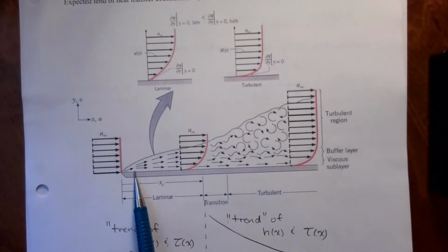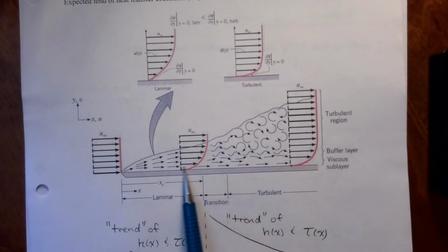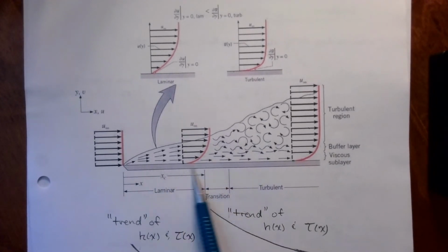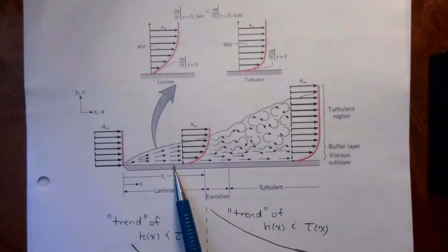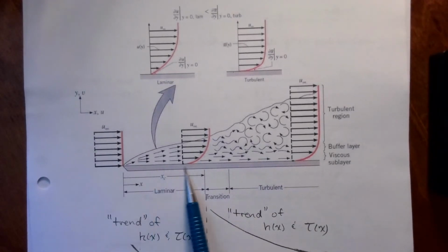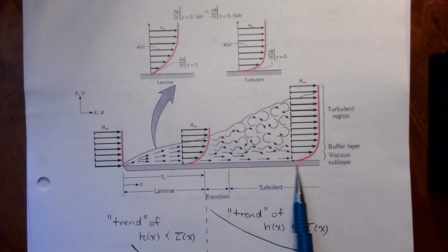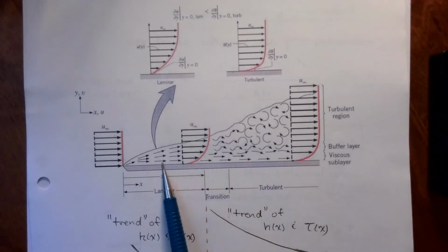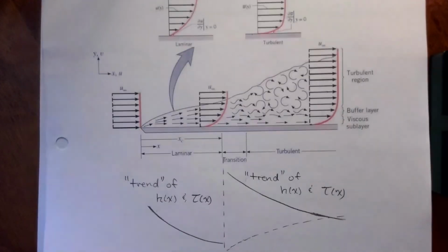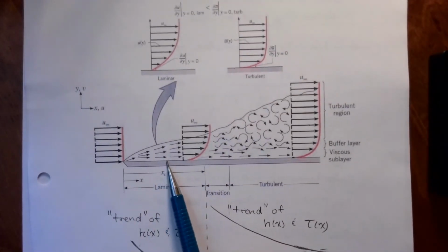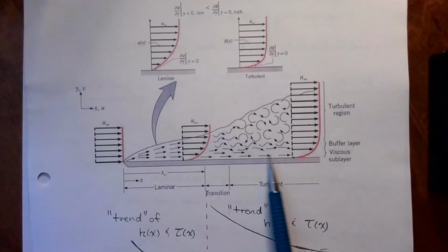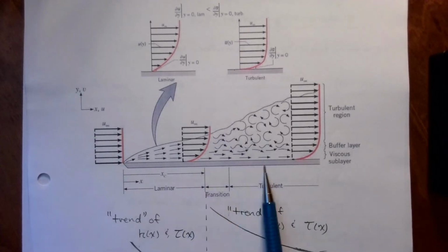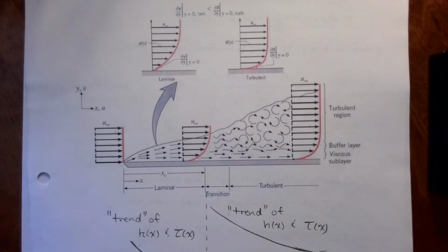Okay, so the temperature, we know that H is changing along the length of this plate because the flow solution is changing. So if we assume that this plate is made of a conductive material, then we can assume that all the energy transitioning this way happens very, very easily. We can expect this plate to be all at a uniform temperature, just one big piece of metal at a uniform temperature. And then Q double prime, the flux, is varying throughout this situation. Actually, it's probably not exactly what's happening. It's probably not an isothermal plate because nothing is perfectly conducting here, but it might be really, really close to that.